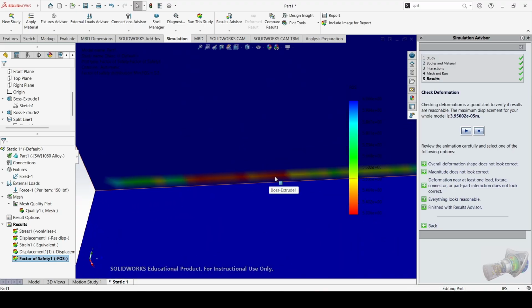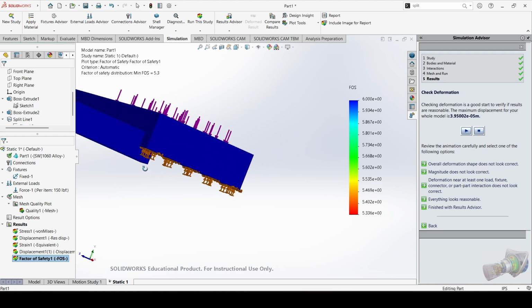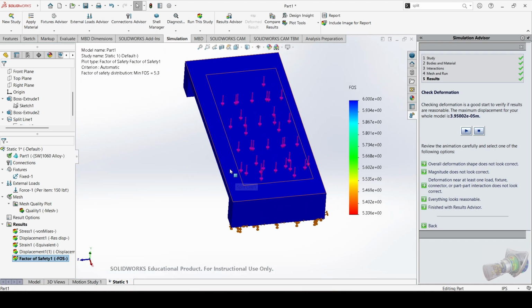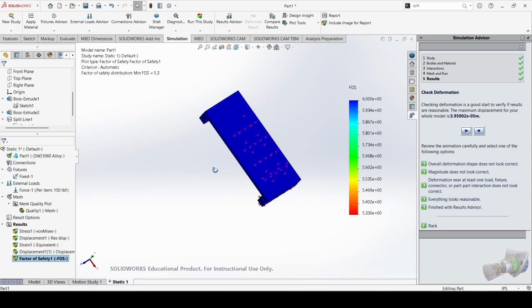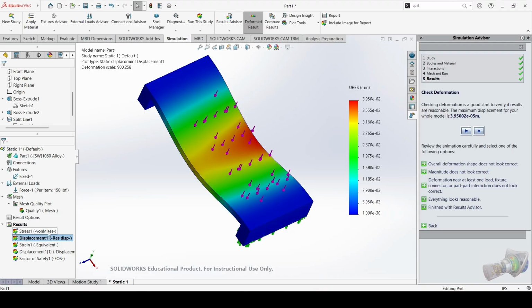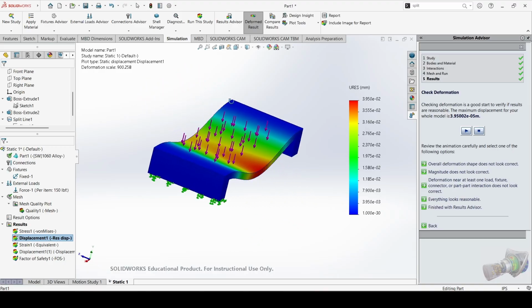As you can see here, that is where that factor of safety of 5.336 is affecting it the most, and probably the same symmetrical over there. So that's what that does. Most of the time, you'll look at factor of safety, you look at the stress, make sure the numbers make sense, and that's one of the main things. Like, is this a result we would expect?